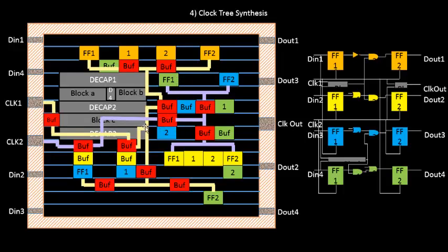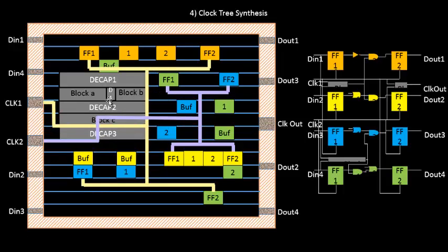The reason is the difference between clock routes with and without buffering. For example, this was the case without buffering. In this case, you see the wire length is very huge, so the number of resistances and capacitances that this clock port has to charge becomes very huge, and as a result you see huge transitions. So we need repeaters. Any person sitting over here, if he sends a shout, that shout has to reach the clock pin of flip-flop 2 without any deterioration.